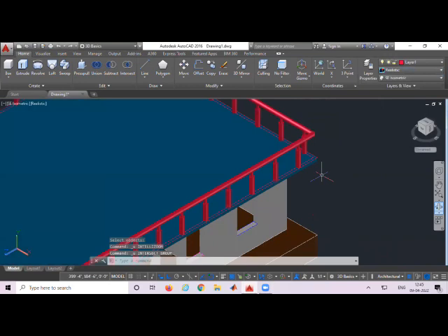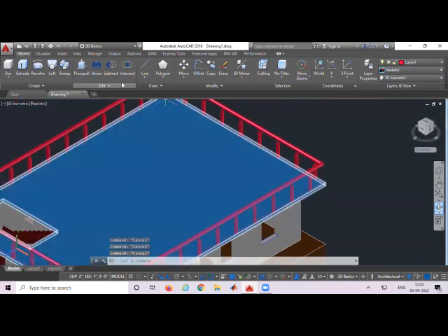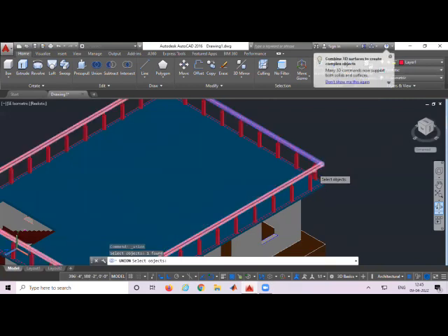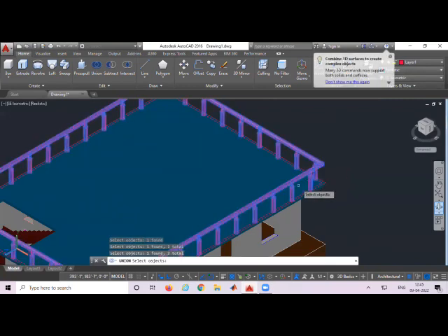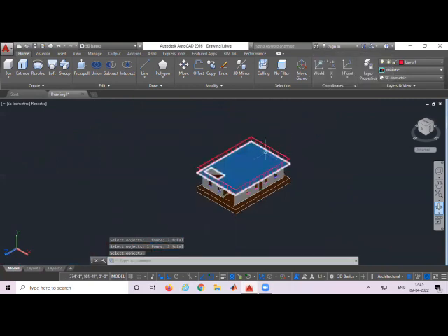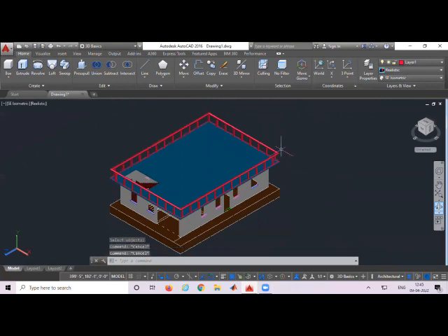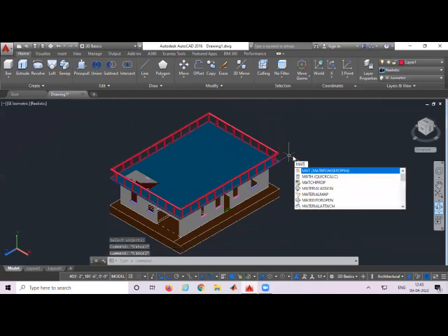So the insert command wouldn't work here. What you have to do is enter union. Union enter, select the whole objects, array objects and railing objects. Even if you do that, the array objects wouldn't be unionized to the railing object because the array objects have to be separated.